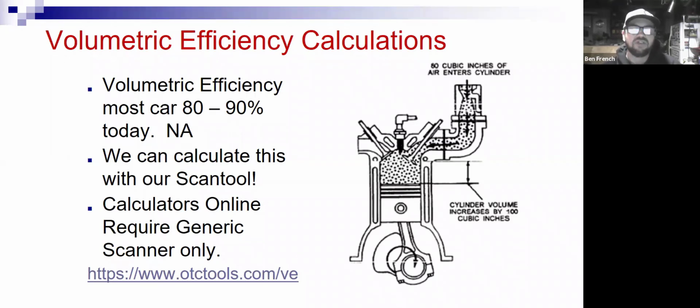Well, we can calculate this with our scan tool based on the mass airflow sensor. And we looked at the website link to do that. And of course, I showed you earlier tonight where it was on our modules to link over to that. Super useful. I find it very nice for diagnosing mass airflow sensors that are getting a little bit contaminated and misreading how much air is actually going in the engine.